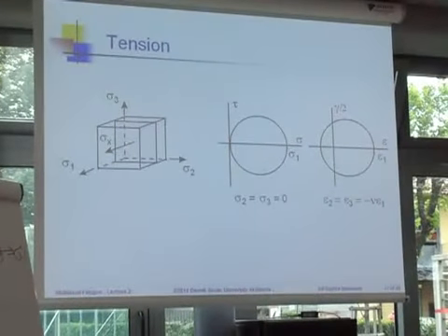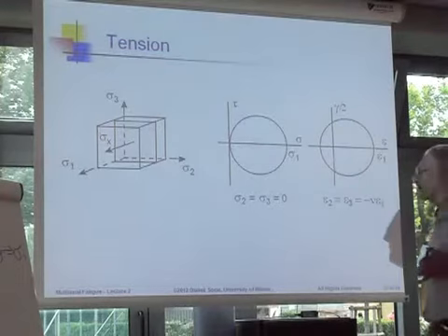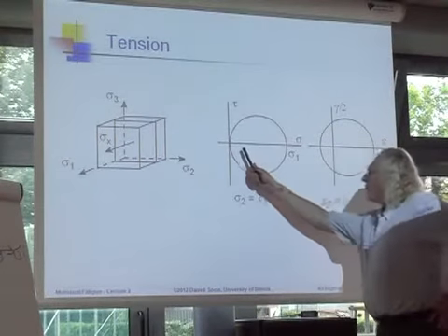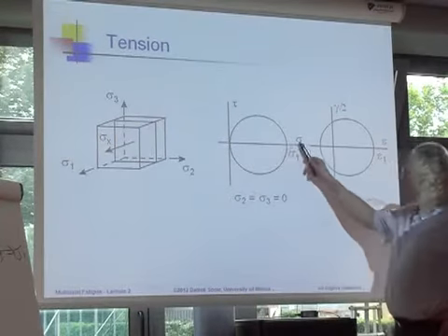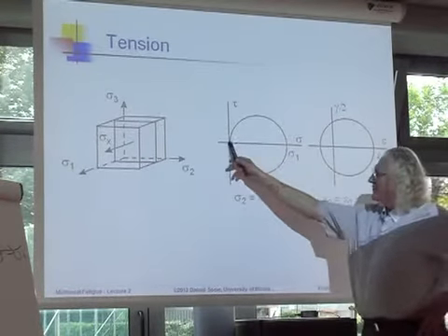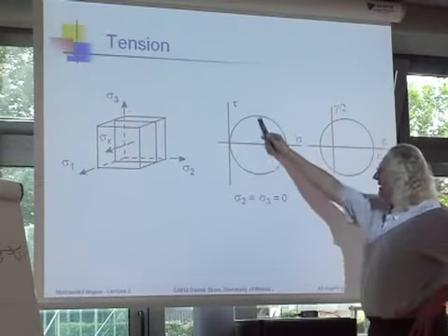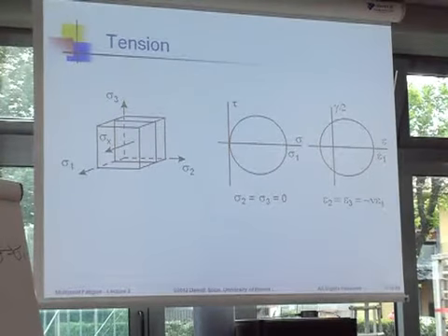So throughout the day I will draw little pictures, and so I like to draw and just review Mohr's circle for different states of stress. So this is just tension, and so we have Mohr's circle for tension, stress, shear stress. Principal stress is in the direction of loading. Second and third principal stresses are 0, and the maximum shear stress is half of the principal stress.